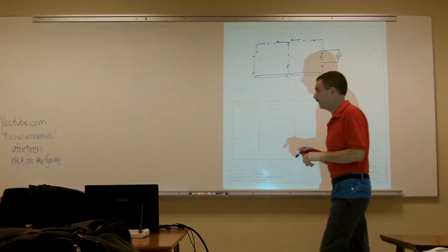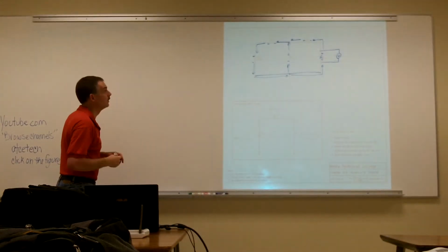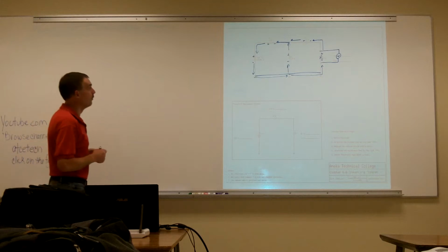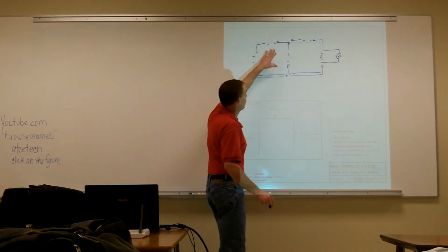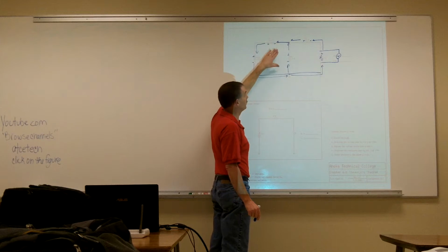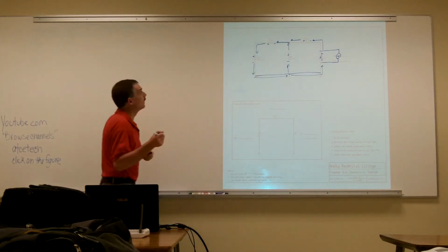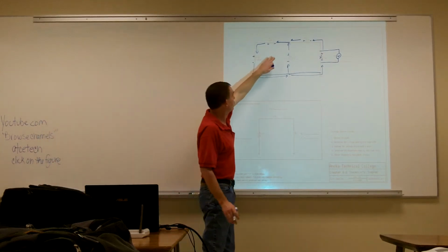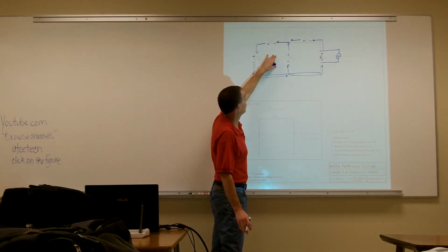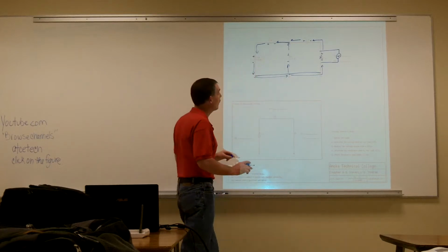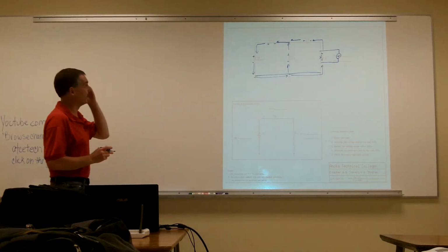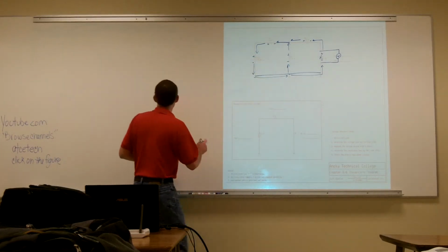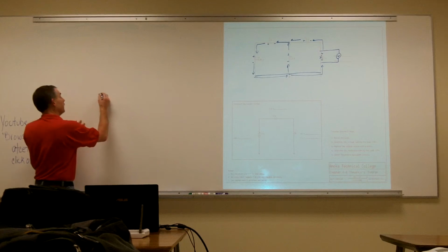Now remember, when we measure across an open, what are we actually measuring? Source voltage. Our source voltage, okay? Now remember, if we have a series parallel circuit, it's the voltage that's going in after the series circuit. So it's still kind of complex to find out what we actually have going on. Sometimes it's easier to straight line your circuit so we can see what's going on. So I'm going to put my power supply on the left-hand side.